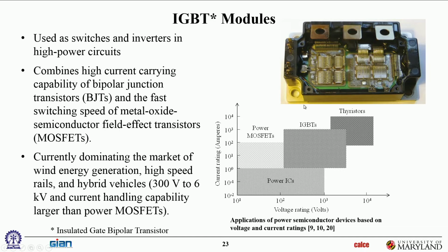The technology is pretty interesting. There were a couple of slides Dr. McCluskey had put in on the silicon level technology over there. In the interest of time, I took that out. But the gates are very specially made over here. The insulated gates are very specially made over here. They're usually trench gates, which is very different from conventional logic ICs. So these are deep gate trenches that allow these guys to operate properly.